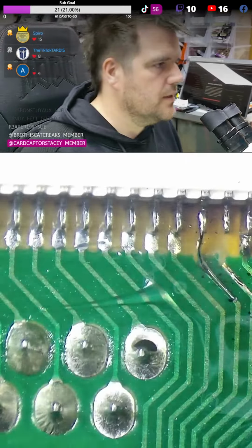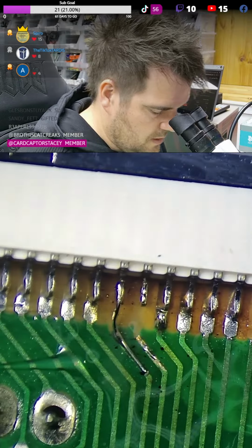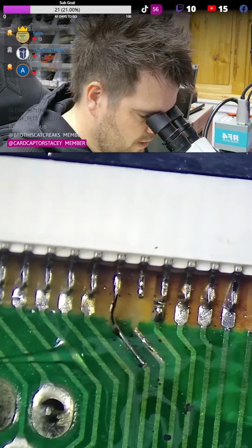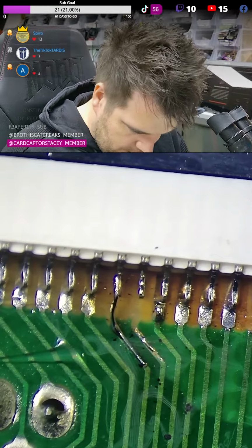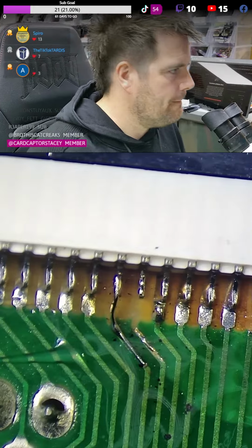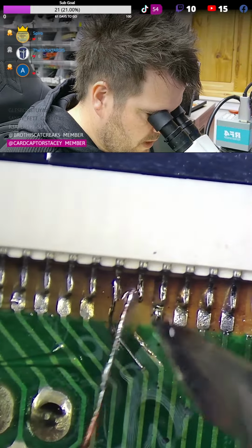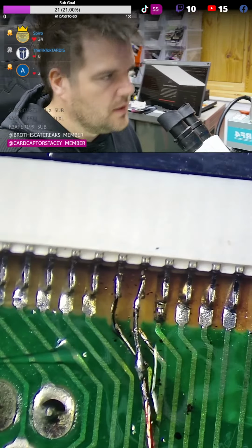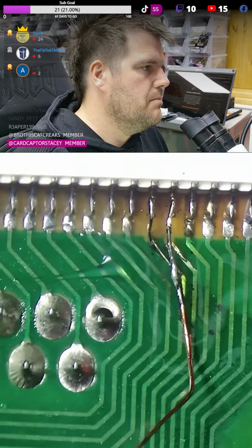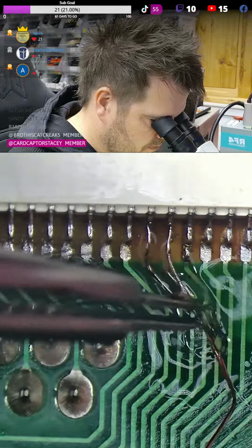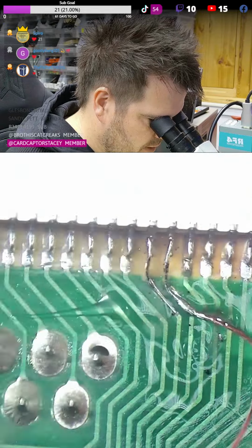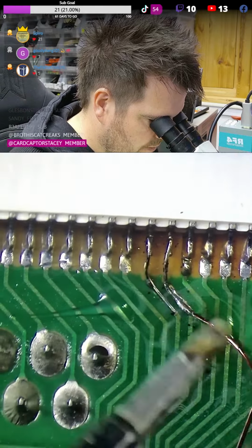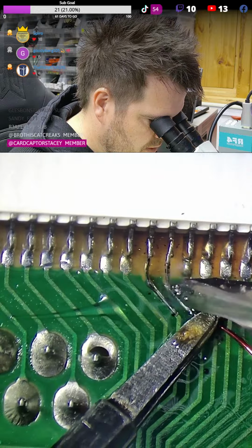We will get that on. So we'll tack onto this pin. Actually, that's got a bit of a bend on. Let's cut that tiny kink off the end. So tack onto there, nice and straight, like so. Bend it into position, so it just looks like the trace, like so. I'm just going to hold down with the tweezers down here, so if it does melt, it should stay in position. Tack on.